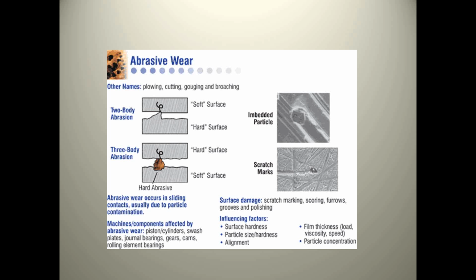Now, one of the things that I've purchased since I've been on my own, we had one at our facility, was a little digital microscope. You can buy a little digital microscope that goes from 100 to 300 power for approximately $300. With that little microscope, you can make a little stand on each side, and you can actually cut a bearing race apart after it's failed, or after you take it off, maybe from a predictive technology, and actually see a bearing surface that looks like this.